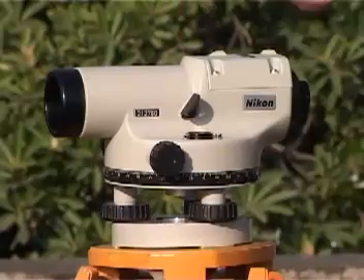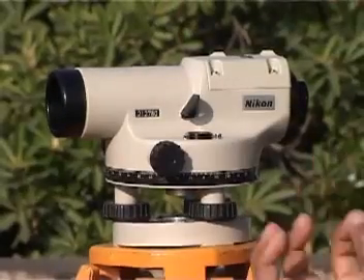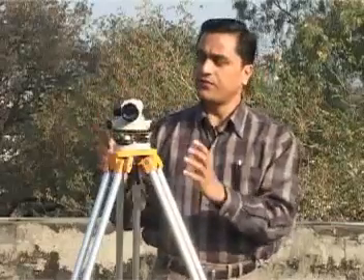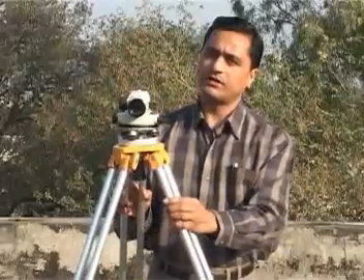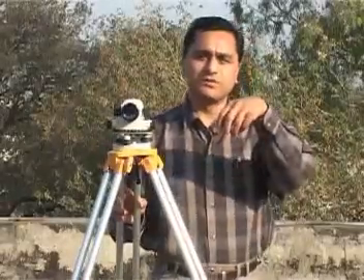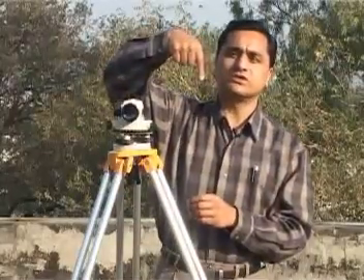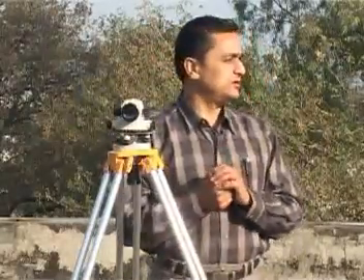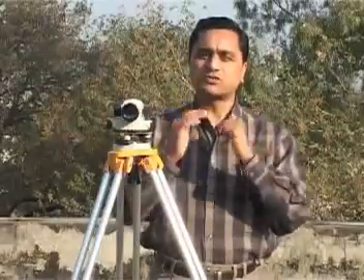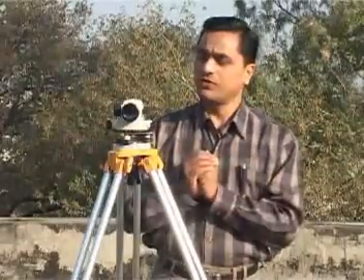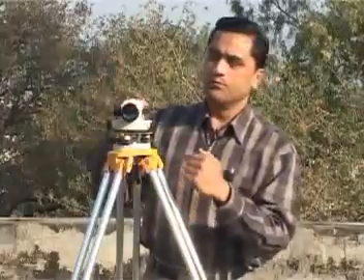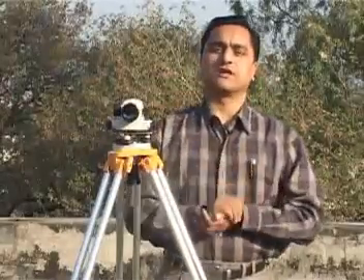Now inside we have an optical assembly which is suspended. Even if I tilt it, that optical assembly will maintain its position. It will keep hanging in its original position. And using that kind of assembly, that optical train, it is possible, as we have seen just now, that we can always see along the horizontal line of sight.